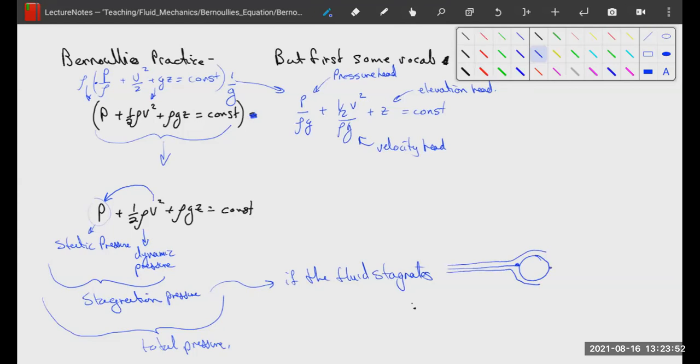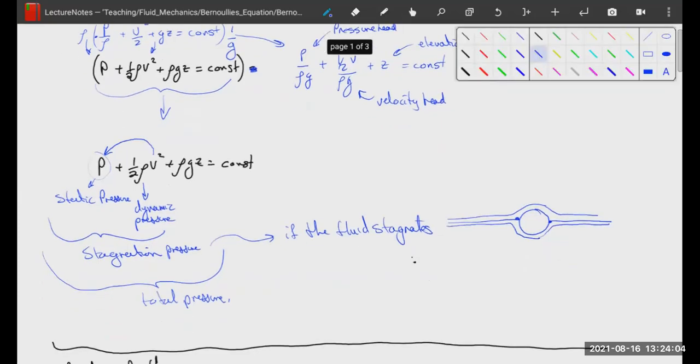There's one on the backside, too, where you have a stagnation point where the fluid is completely stagnant, and then a streamline that leads away from it, right? It goes like this. So at that stagnation point, we get the static pressure, right? But the velocity is zero, and all of that kinetic energy went into our pressure. So we're now measuring at least these two parts of the energy of a fluid combined, right?